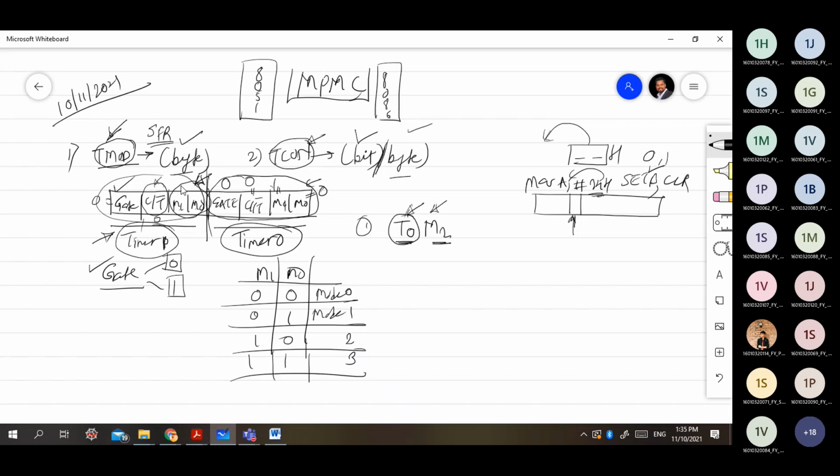Fine. And it is just regarding Timer 0, so we can put the upper bits as 0, because they belong to Timer 1 and nothing is said about Timer 1. So now try to understand. This is the value which you have to load into TMOD: 0000 and 0010. In short, this becomes 02H.